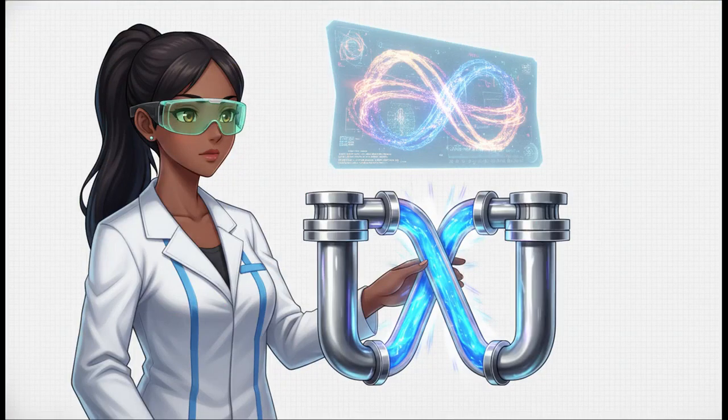But what about when we absolutely must know the exact weight of the fluid, like in precise chemical batching, when we need to measure the actual mass passing a point per unit time, not just the volume? Engineers rely on inertial mass flow meters. The real heavy hitter in this category is the Coriolis mass flow meter. It uses a vibrating U-shaped tube that physically twists due to the Coriolis effect as fluid pushes through it. By measuring that exact twist, it gives us a direct, highly accurate measurement of mass flow and density, completely regardless of temperature or pressure changes. There are also thermal mass meters that use heat dispersion, plus impeller and twin turbine styles for different applications.